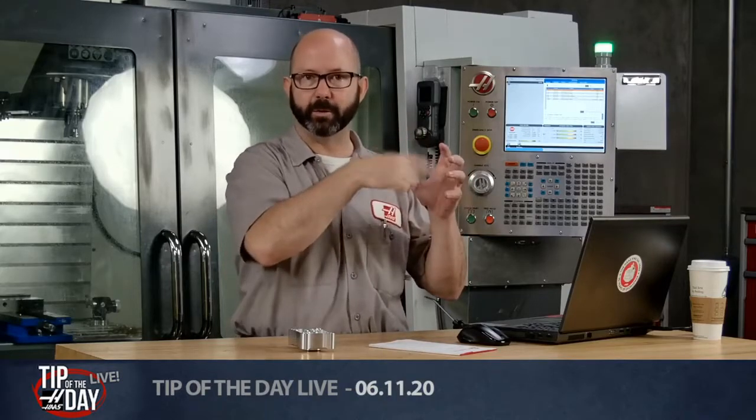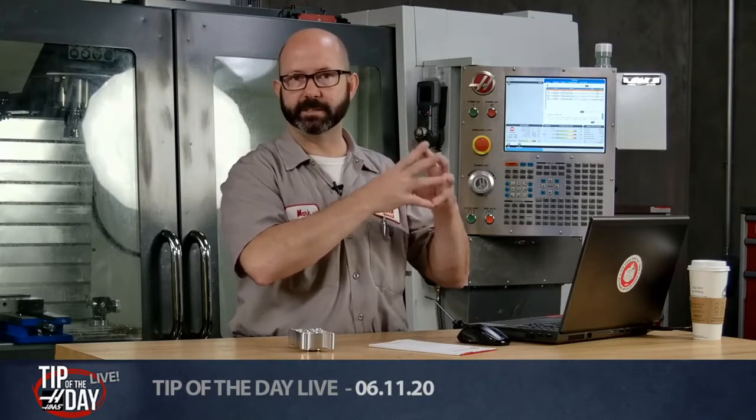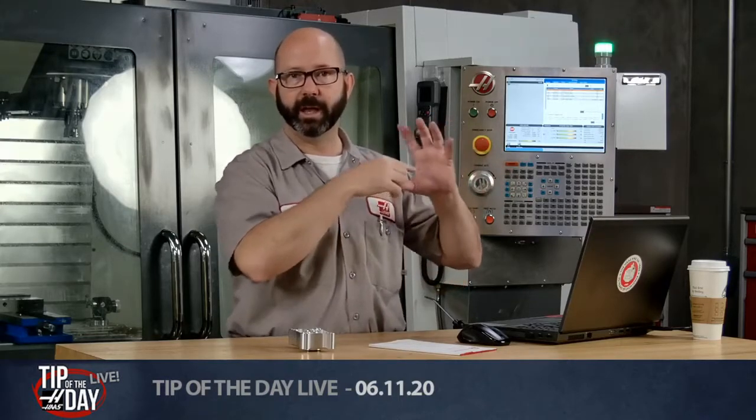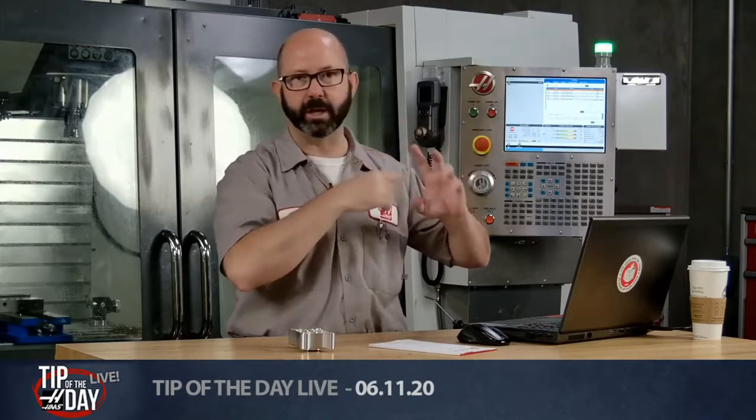But you can actually line up the C-axis, which is like a rotary on the lathe. The spindle is not spinning round and round. It's working like a real rotary. And you can align the C-axis to the M19 P0 orientation. And so where all those numbers meet up, you have to understand that if you're trying to do perfect handoffs. But it gets complicated. Make a great video. We should make a video on spindle handoffs, right?